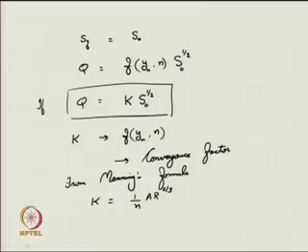They all can be employed to determine y n, but how can you arrive at that? So, your conveyance factor K is equal to 1 by n A R to the power of 2 by 3, we can write it in that way. Again proceeding, I can write the same relation now. A R to the power of 2 by 3 is nothing but n into Q by S naught to the power of half.